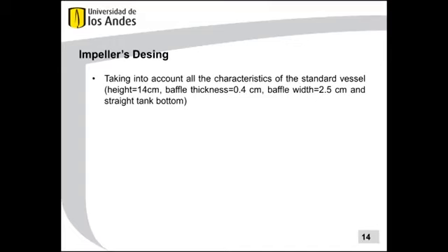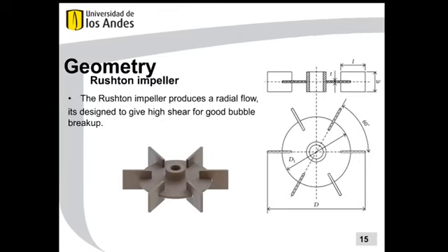So, impeller and vessel design. The vessel used for the analysis was small, probably a vessel you would use for research purposes, but anyway there are many ways to scale up agitation and mixing. This is the common Rushton impeller. It has 6 vanes perpendicular to a rotating plate. The dimensions could vary, but you get the main idea. The impeller has been around for many years now, but it is still the impeller with the higher shear rate.